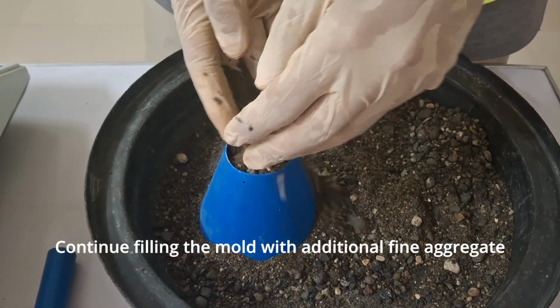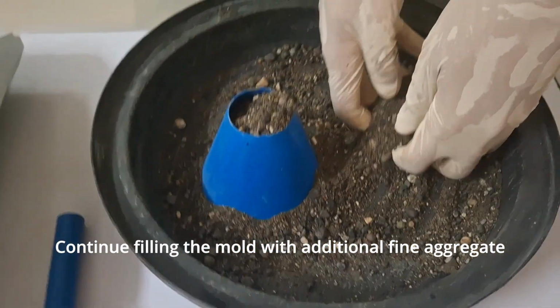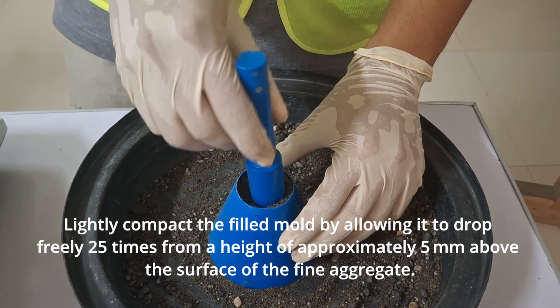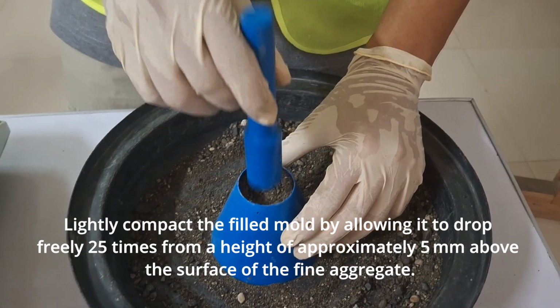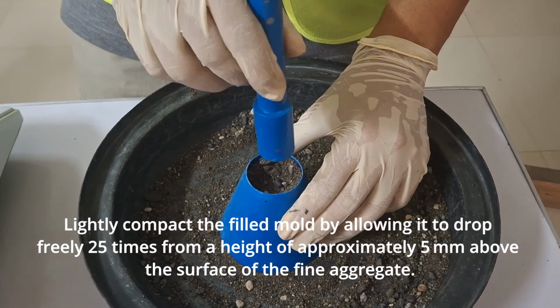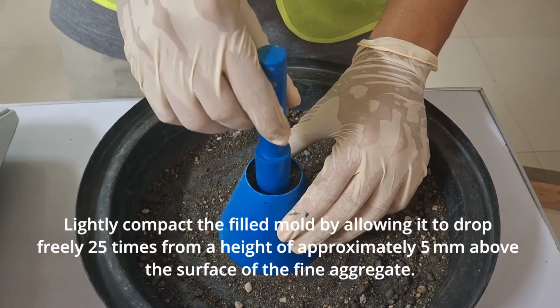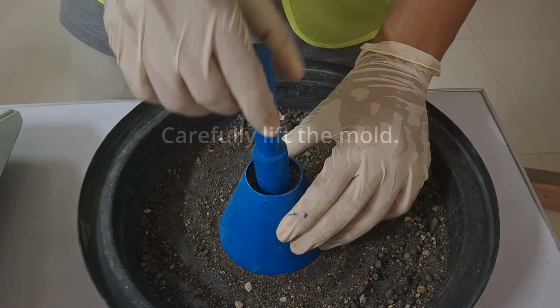Continue filling the mold with additional fine aggregate, tamping lightly as needed until the mold is full. After that, lightly compact the filled mold by allowing the tamper to drop freely 25 times from a height of approximately 5 mm above the surface of the fine aggregate.